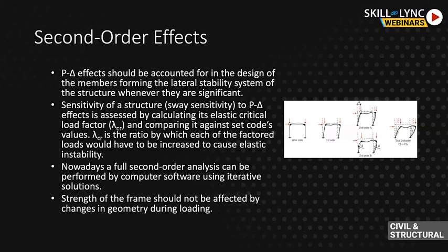So how do you decide how sensitive your structure is to P-big-delta effects? Basically, by calculating something called lambda crit, which is the elastic critical load factor, against specific set values in the code.